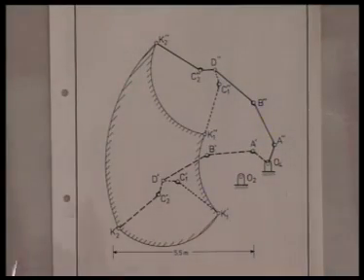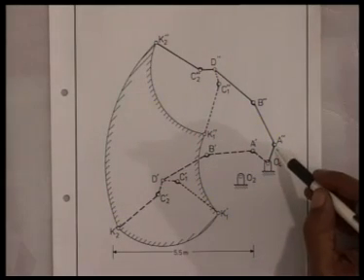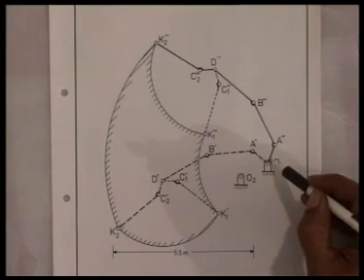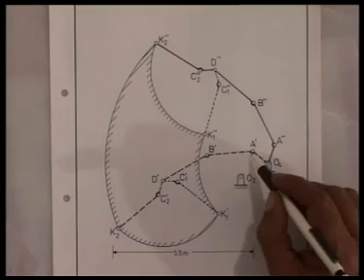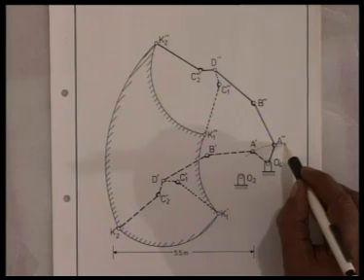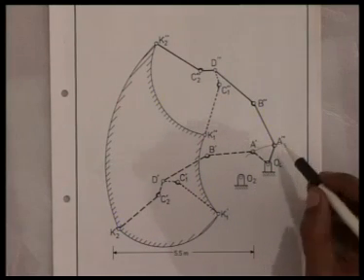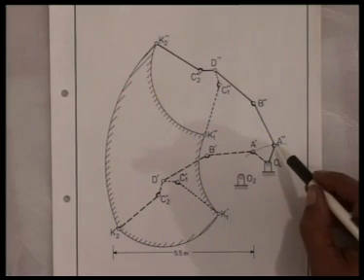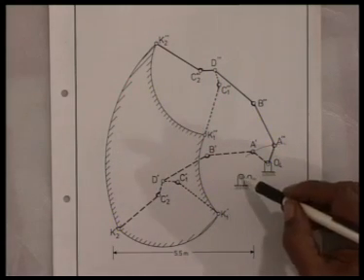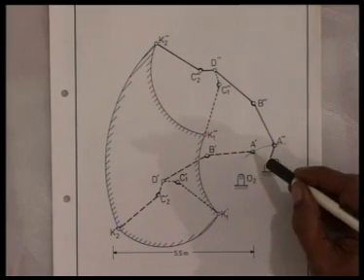If we look carefully at the original diagram, we can see that this distance O4A never changes because they belong to the same rigid body. Consequently, A lies on a circle with O4 as center and O4A as radius. The maximum distance between O2 and A, which is given to us, locates this point. The minimum distance between O2 and A, which is again specified in the problem, locates this point.